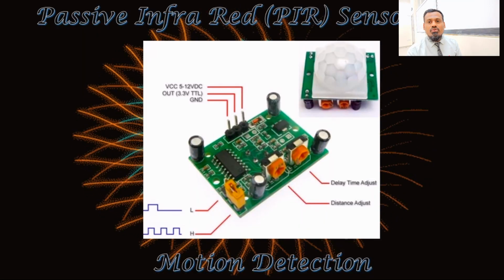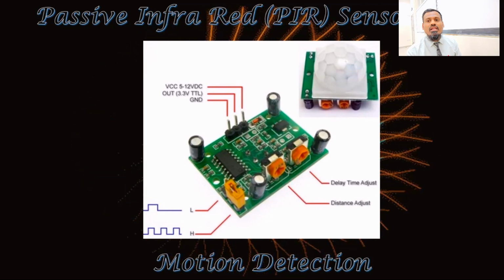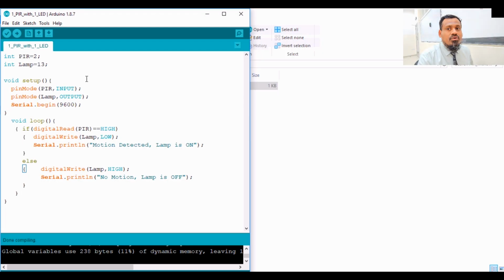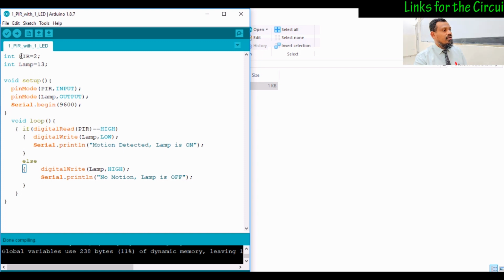Now we will discuss the Arduino coding to utilize this motion sensor for controlling the electrical lamp. So this is the code we are going to use for controlling the electrical lamp. In the code, you can see that we have declared the PIR sensor to be on pin number 2, and we are going to connect the lamp through the relay module to pin number 13.